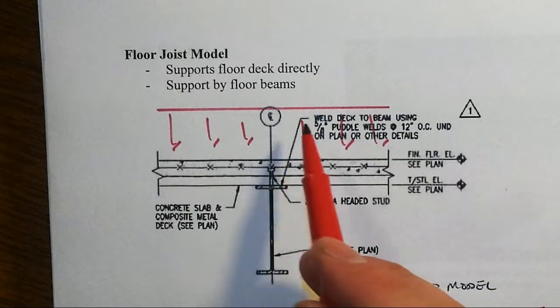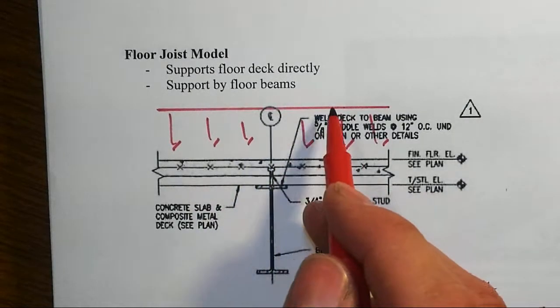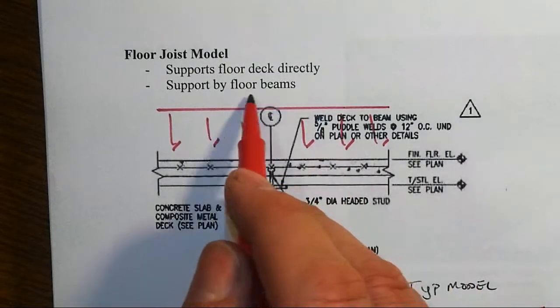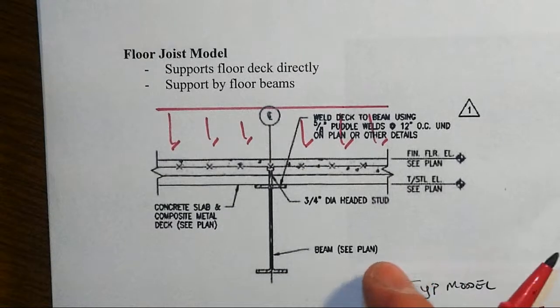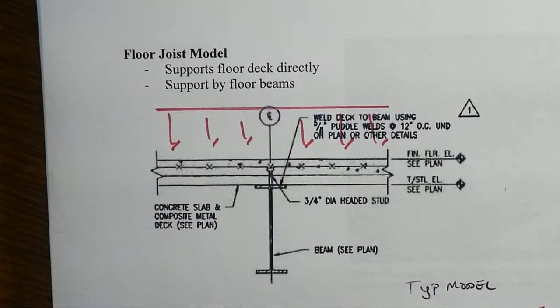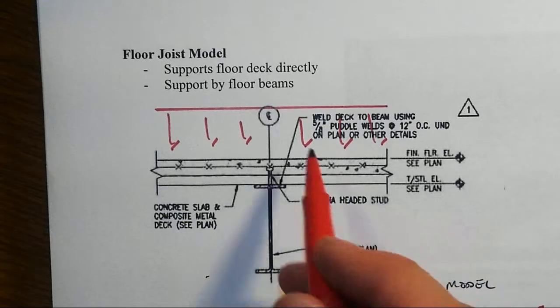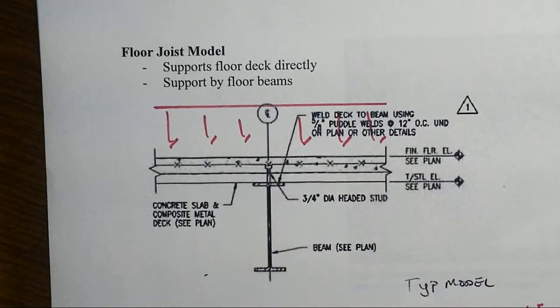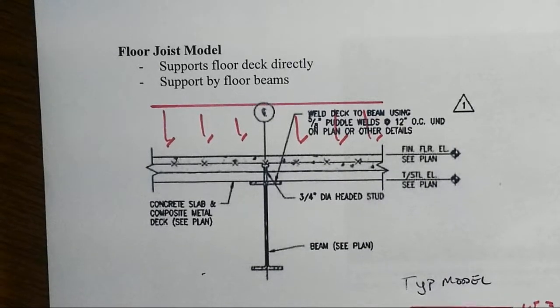And in an office space, the live load would also be about 50 pounds per square foot. So that might be a total of D plus L, 100 pounds per square foot, and then multiplied by, if I have these spaced every so often, say every 5 feet, I would take 2.5 feet one side, 2.5 feet the other side of this load, and effectively call that then the distributed load here, which would be this floor pressure times the tributary width.